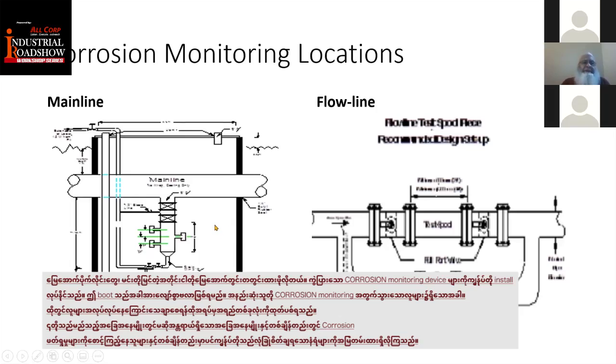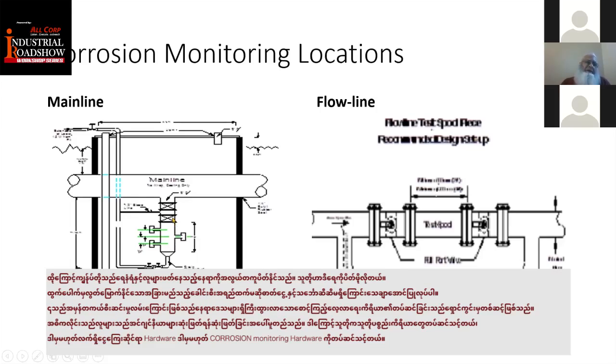At least when people go for the corrosion monitoring, because mainly we install the ER probes in there, we have to eject the entire liquid from there to make sure that the people working there are not subjected to any kind of hazard situation. At the same time, people there monitor the actual corrosion readings. And we always prefer to have 2 safety valves there, not one, in case one is plugged or stuck, so we can easily close the other valve.